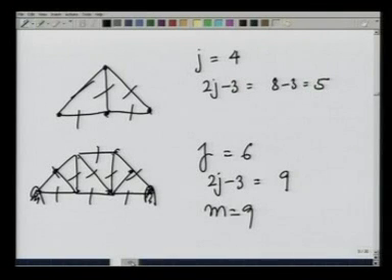You notice that both the ends are put on a fixed point. Actually, this makes the system indeterminate because the number of external forces is now 4. We could make it determinate by putting the right hand side of the system on a wheel or on a roller. Let us take one example of this.